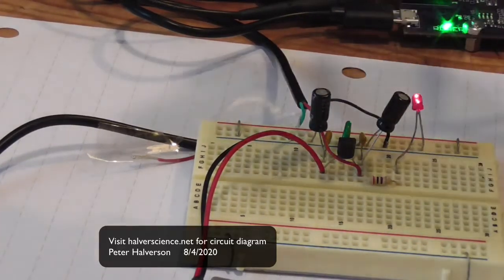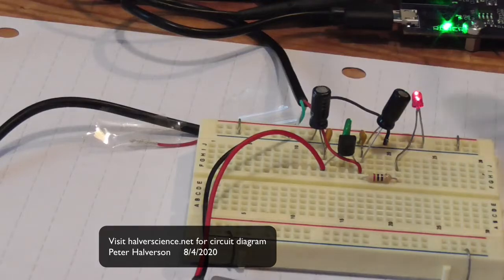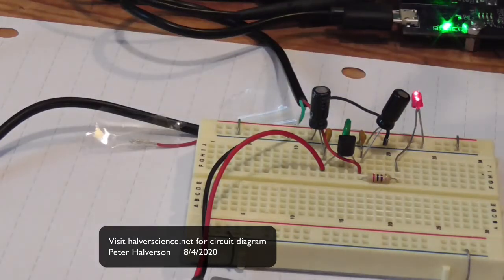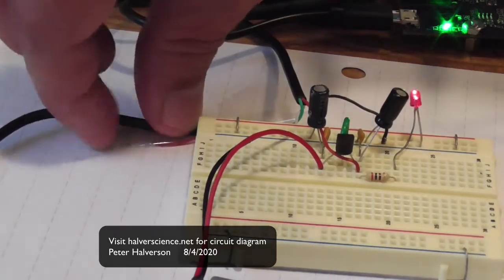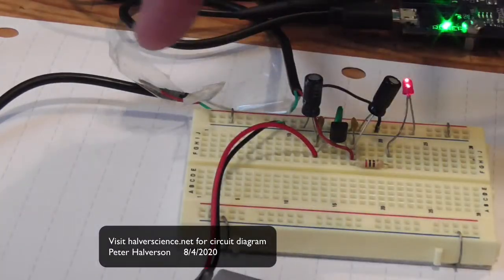So the signals for programming the FPGA board are still getting to the FPGA board. It turned out that the data signals were on the white and green wires, and so I just continue the white and green wires straight to the FPGA board. But the power was on the red wire. So what I did is, you see here, the red wire disconnected. I'm not using the power from the computer.